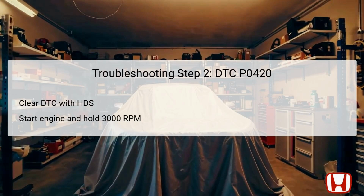In Step 2, clear the DTC using the Honda Diagnostic System, HDS. This system allows for a comprehensive diagnosis and troubleshooting of Honda vehicles. Once the DTC is cleared, start the engine and hold the engine speed at 3,000 RPM without load, which means the vehicle should be in park for automatic transmission or neutral for manual transmission.